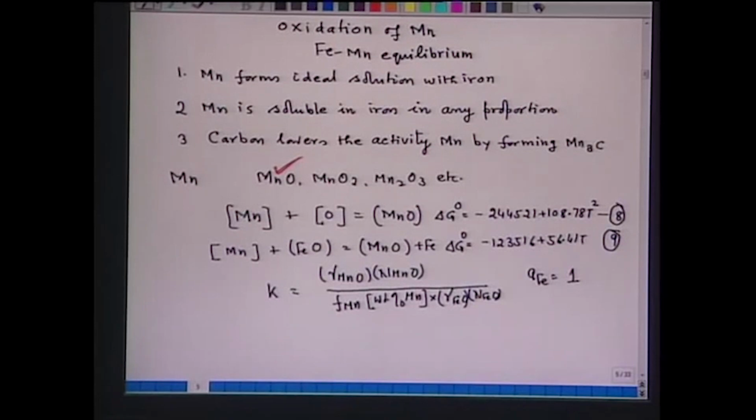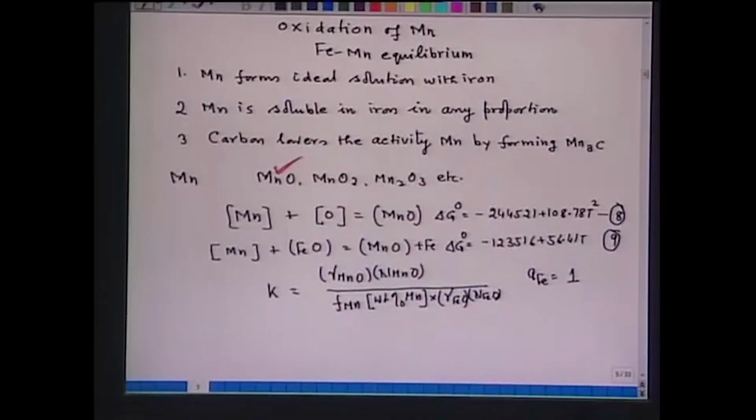Now, it is already known, I believe, to all of you that slags are concentrated liquid solutions, and the activity of the components in slag obeys Raoult's law, where activity is equal to gamma into mole fraction, and the molten metal or liquid steel are dilute solutions and they obey Henry's law. Accordingly, gamma MnO is the activity coefficient of MnO on the Raoultian scale, and Fmn is the activity coefficient of manganese on the Henryan scale, or more precisely on the 1 weight% standard state.